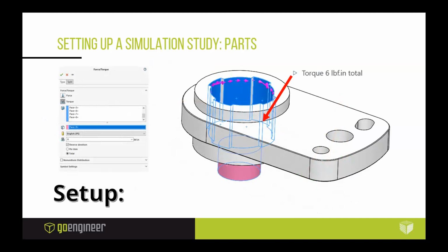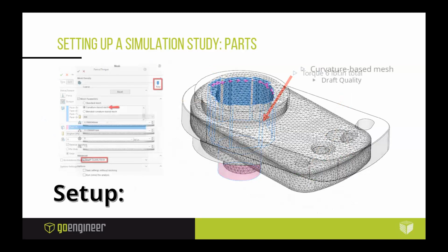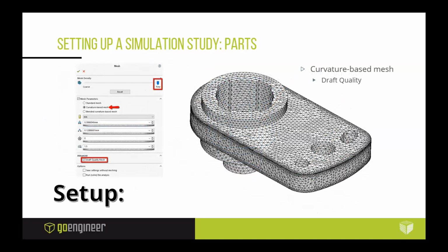And again, this is going to be for maybe ideally an impact dynamic analysis. So I bumped it up a couple of units to 6 to see. I want to see where the stress hotspots are to start. And that's the goal for this static study. And then I'll set this thing up with a mesh.